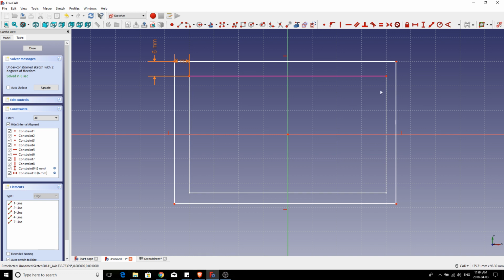Well, the same way that we did when we made our first sketch. We're going to use symmetry. So let me pull this out of the way here so it's not confusing us. I'm going to select my point right here, select my point at the bottom, and then I'm going to apply symmetry around this axis right here. So let's hit the symmetry button. Boom. See how that's repositioned? That's looking pretty good. Now we need to do the same in the other direction.